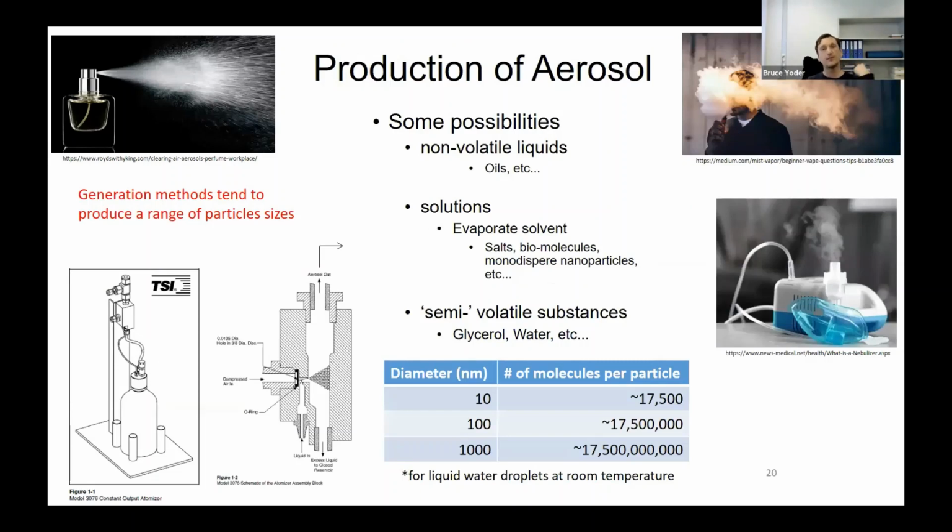There are several ways to produce aerosol particles, and we come into contact with many of them in our daily lives. They often involve spraying, atomizers, nebulizers, electrospray, to name a few. With the exception of the gas dynamic virtual nozzle at the very end of the talk, all the aerosol examples that I show today involve atomizers, which are, simply put, continuously flowing perfume bottles, schematically shown here.